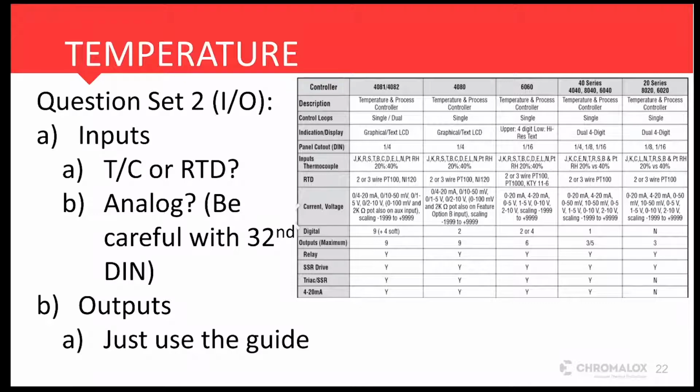And then for the outputs, I really just use the guide. You want to hear if they're planning to use this controller in conjunction with a contactor for relay output, or an SSR or an SCR for the SSR drive. Your customer should know, or if not, you can give some gentle guidance on what type of output you'll need there. But inputs and outputs are a strong second place to start to really narrow down your options.